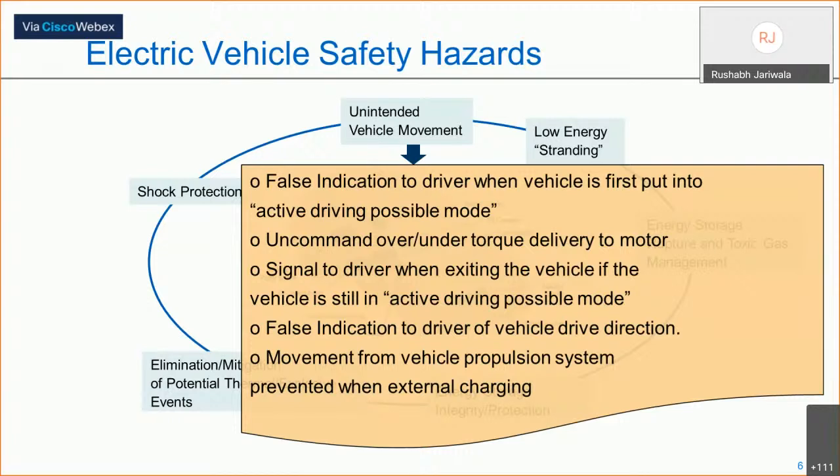So when the driver just wants to say, okay, start the vehicle, at that point of time, if there is a problem with the inverter or somewhere in the design or logic, and it simply releases the torque immediately, then that is one sort of hazard, and it is having enough energy.